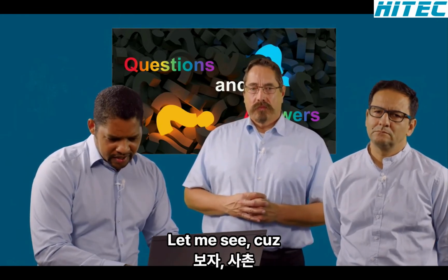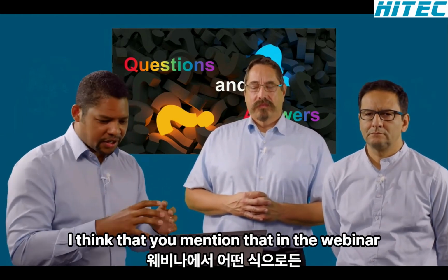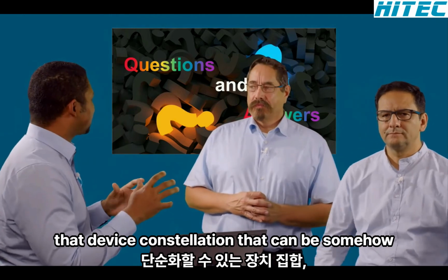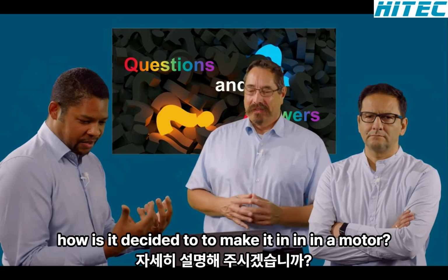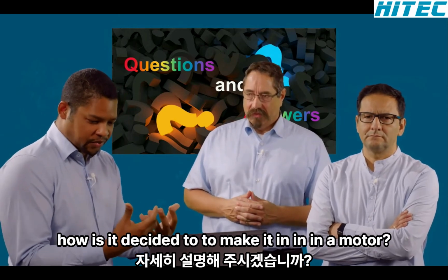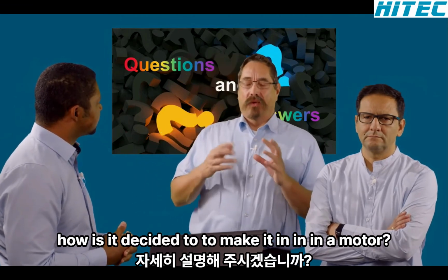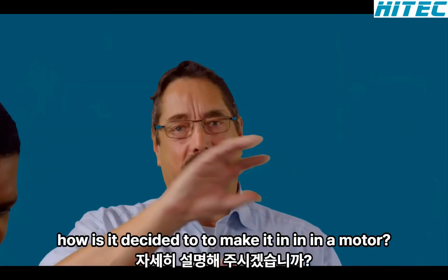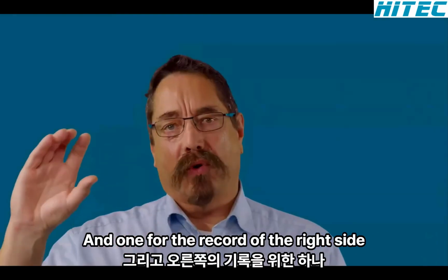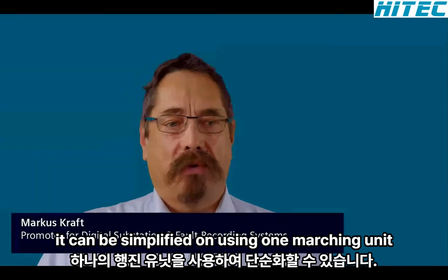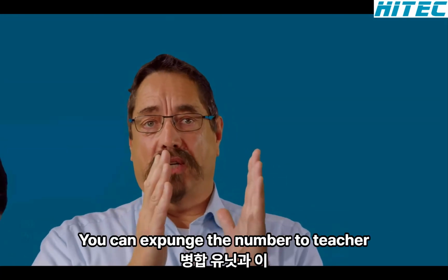Marcus, I think that you mentioned in the webinar that there's a device constellation that can be somehow simplified. Can you elaborate on that? They're asking how would it be possible to simplify what has been presented? It's possible. As I said, I decided to make it in a more granular way, to have 2 merging units, 2 protection relays, and 1 fault recorder on the right side. It can be simplified by using 1 merging unit base module plus an expansion module for feeder number 2.